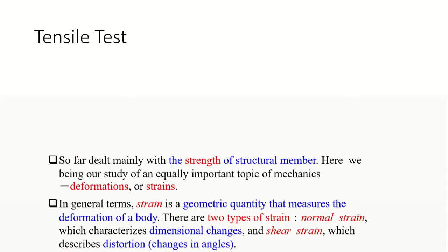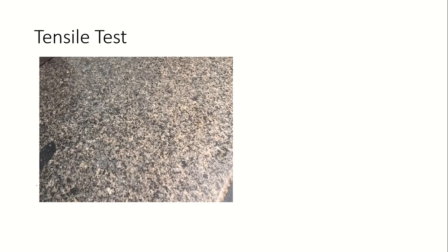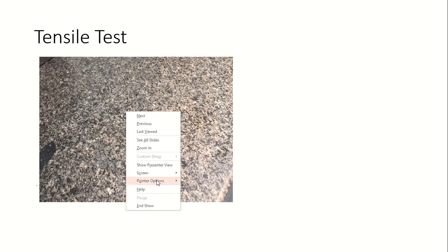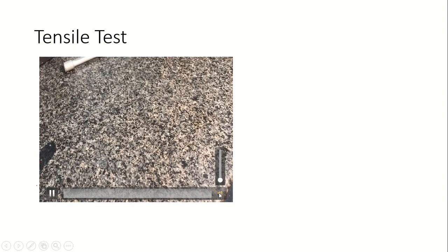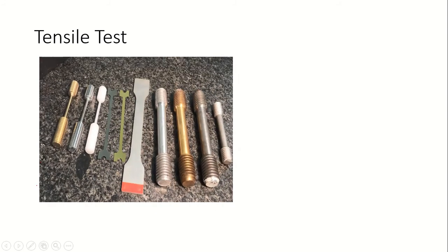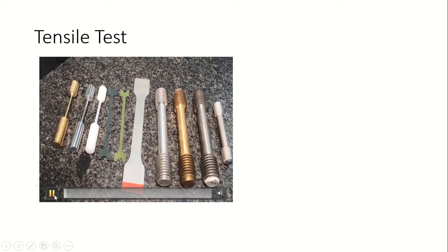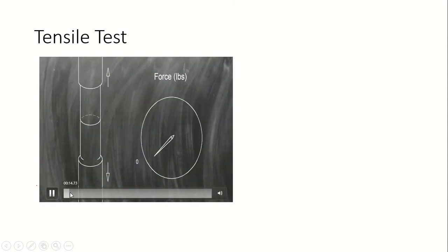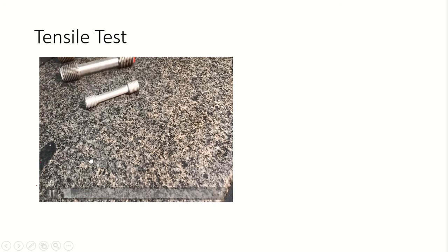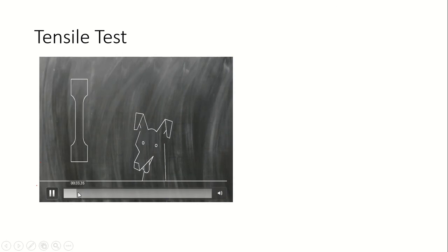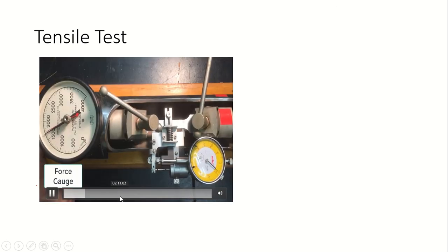Okay, now let us go here to see how tensile stress will be conducted. Okay, so please observe the video here. So these are the different material specimens for different components, how you can find out the tensile stress. Okay, so these are all tensile test specimens. So here you can say this is a bronze, aluminium, steel, then flat aluminium member, then flat strips, etc. Okay, so here if we apply the force, due to the ductility property, what will happen here? Necking formation will take place. With that you can go for finding the stress, guys.